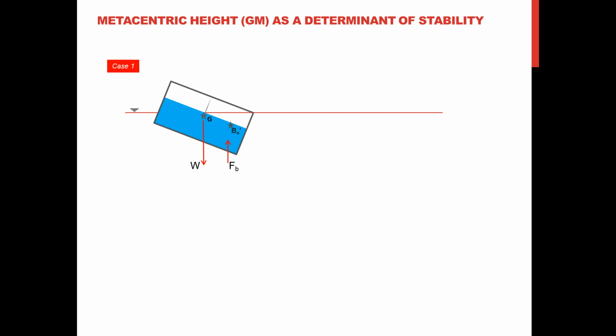So in here we draw an axis parallel to body and then project this upwards, okay, to intersect with that line of action of the body's axis. And this is metacenter. Now, originally we have this location as our center of buoyancy. Of course, this will be the angle of tilt.